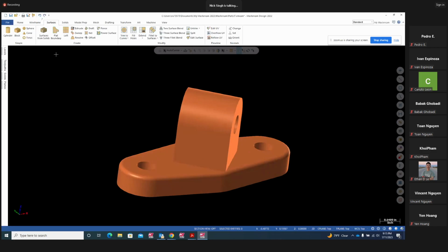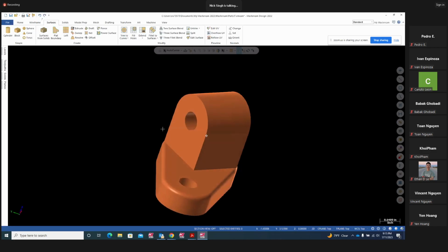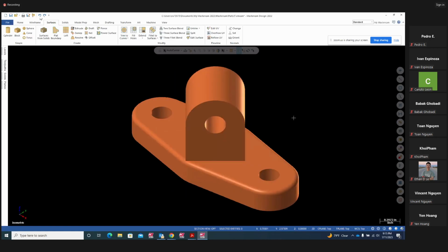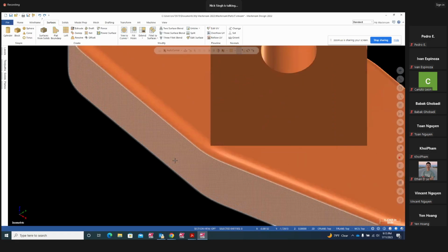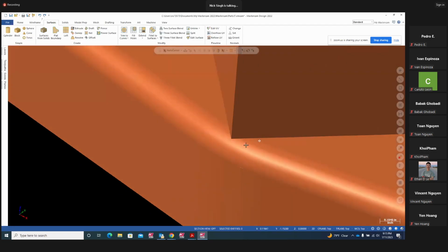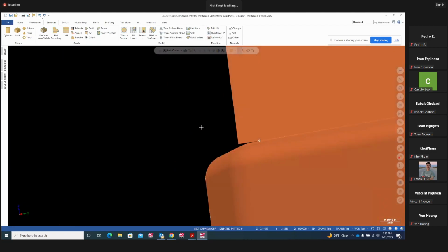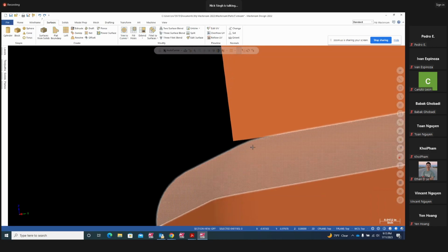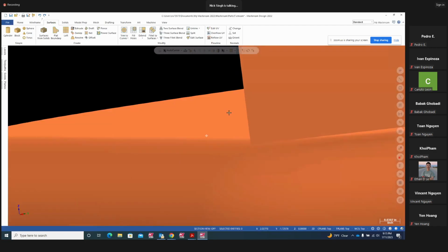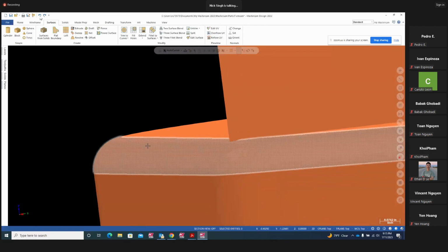Let's do it. Here we go. We're going to do one more time. Isometric. Because you cannot get this fillet on the bottom until you get this corner fillet, because this is going to blend with this over here, guys. That's what it is. Look at how that fillet is separated from that. So we have to make that fillet first. Then this is going to blend with this fillet right here, the corners. So this has to cut first, this corner, the one we are doing right now.